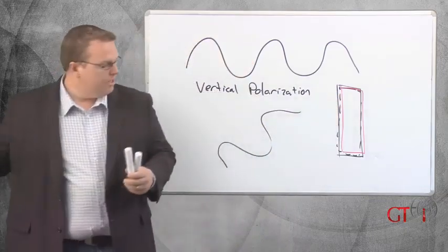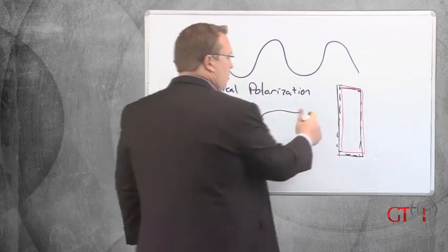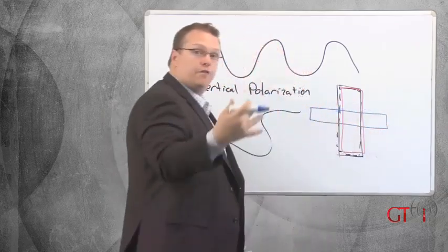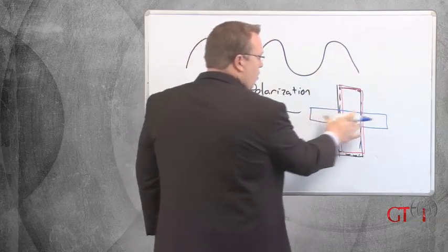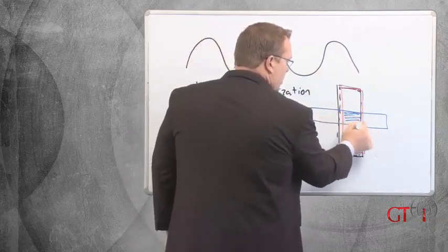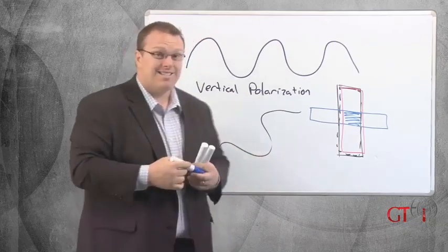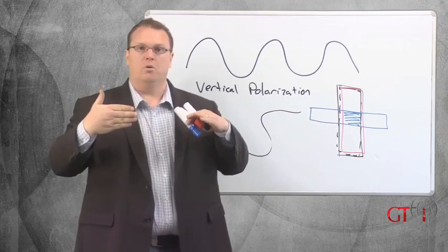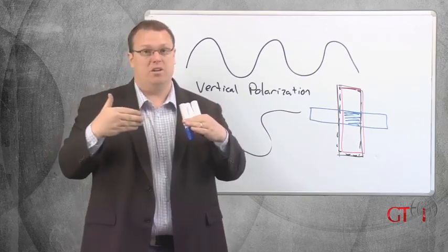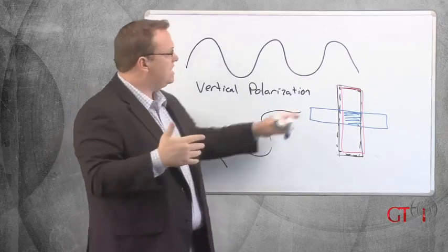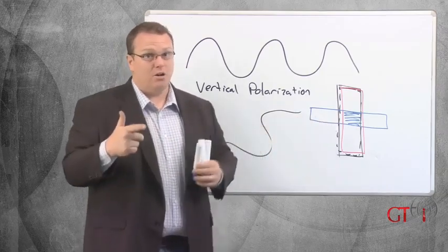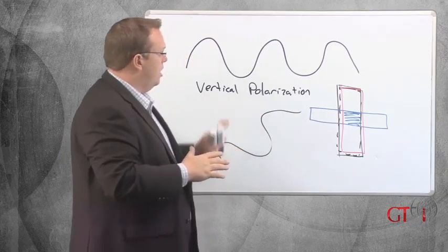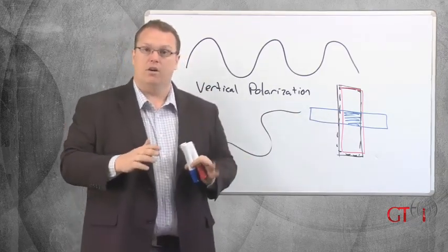But if we switch colors here, and let's say now we're going the vertical to the horizontal, you'll see that the vertical being in red, the horizontal antenna will only receive that amount. That's not a lot. So can you technically get a connection with one vertical and one horizontal? Yes, if there's enough signal strength, but it has to be a lot. There's like 30 decibels of loss. If you go back to your RF math, you remember 30 decibels is a ton. That is a lot of signal loss. So outdoor polarization is very important.